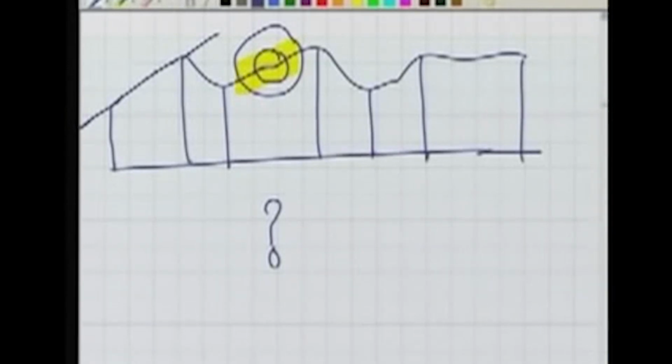This depends upon how accurately you want to represent the ground onto the sheet. If your concern is you want to represent each and every variation of the hedge, yes, we should take an offset. It also depends upon the scale. What is your scale? Because you will remember, we are talking about the plotting accuracy.